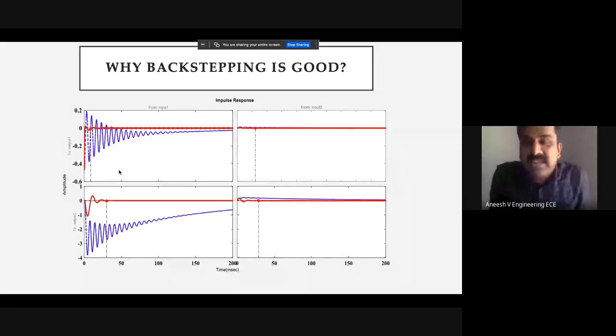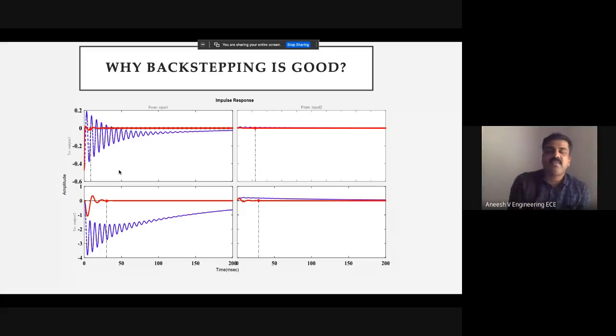Here, in the nonlinear structure, we didn't use any linearization technique or any other mechanism. We simply divided the system into aileron, pitch, yaw, and roll. Like that, we made the subsystems and implemented the controller. From that, we got a drastic improvement.